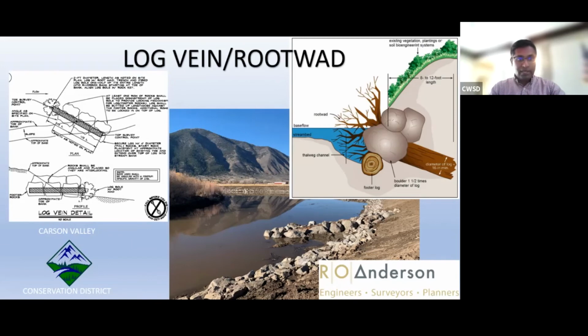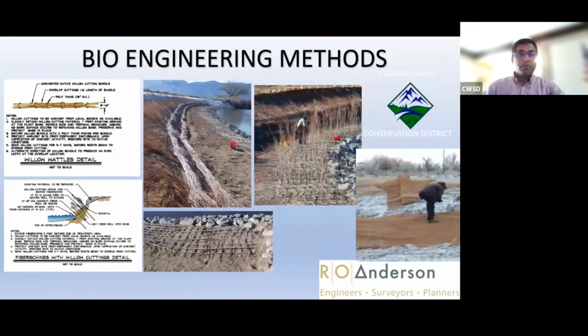But they work very well as long as they're installed correctly. They also use ductile anchors to anchor these so that they don't float away. So that's one of the things you need to remember if you're doing this. Put a lot of rock around, mostly downstream, so we don't want those to be washed away.